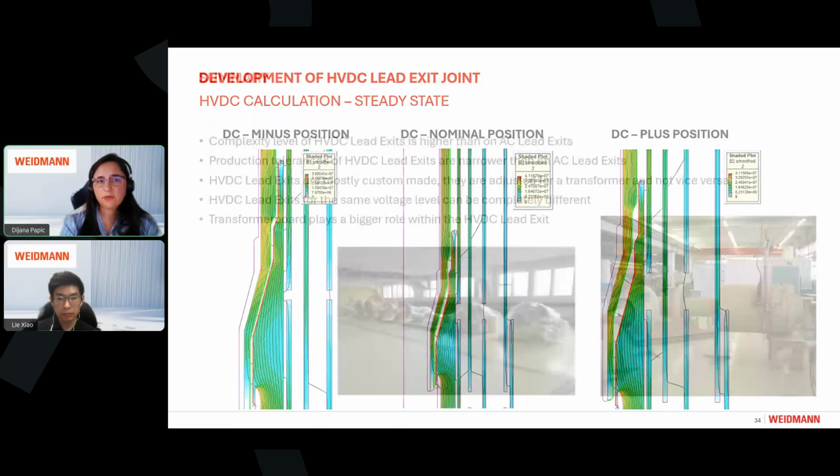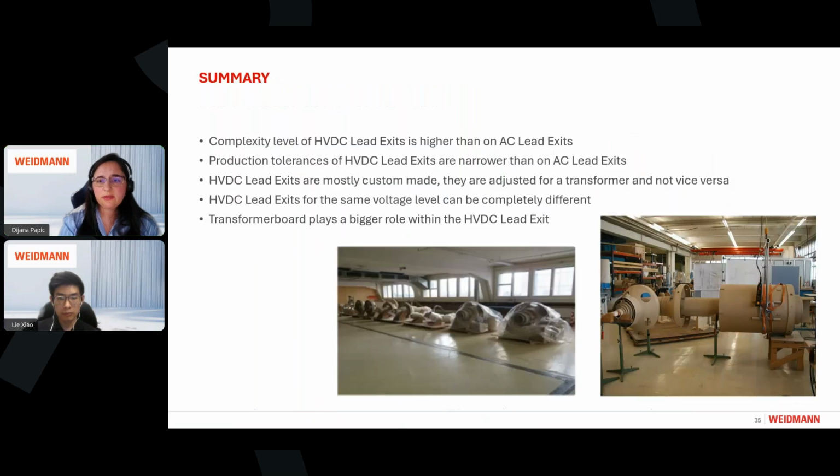And to conclude, the HVDC lead exits are very similar at first glance to the AC lead exits, but their complexity is much higher due to a huge amount of layers of barriers and insulation compared to AC, and narrow tolerances.